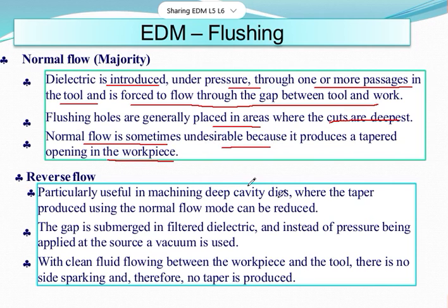But if I look at the reverse flow, it is particularly useful in machining deep cavity dies, where the taper produced using the normal flow mode can be reduced.